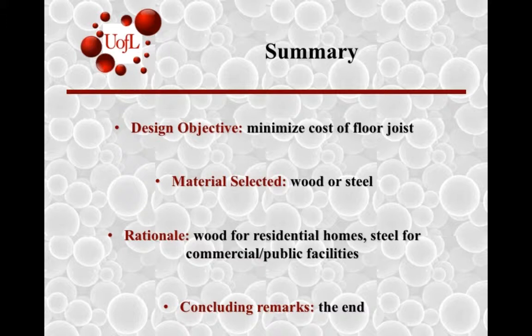So in summary, my design objective was to minimize cost of floor joists. The material selected, the cheapest option was actually concrete, but since it's not great in tension and it's really heavy, I would not recommend that as beams in your house. So I would recommend wood or steel.